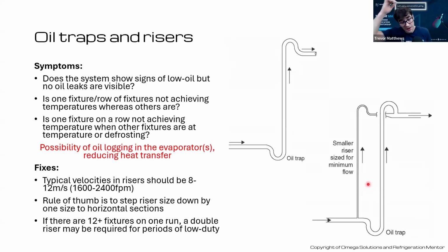So sizing that, I've only seen a few of them out there myself in the supermarket industry. You don't see it too often. Rarely, no. I mean, much larger, you're talking 40,000 square foot stores and above, where you have possibly 12 open-fronted display cabinets on a single riser. You can get some large swings in duty there. If some are at temperature, if night blinds are down overnight, or somewhere on defrost, and you still need a decent amount of product being cooled in the grand scheme of things, it makes sense to go down this route here.